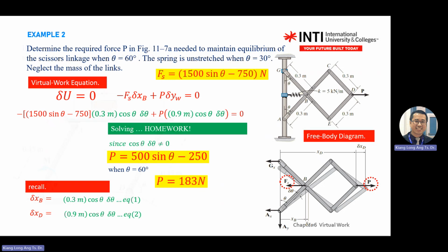Okay. So the rest, you will see there's a pattern. It is important that you see the steps. First you draw the free body diagram. Then you imagine what is before and after. Find this small displacement. In this case, it asks you for the force P, so you focus on point P. But something happens to the other bodies, so you find the small changes and relate them to the small changes of the three small triangles.